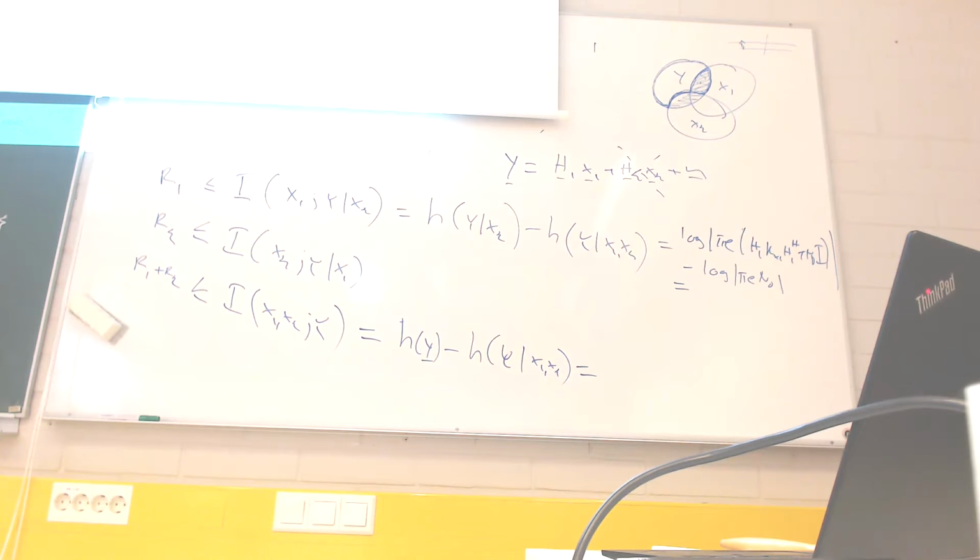You have a pentagon for this pair of transmit covariance matrices, but a different pentagon for a different pair. To come up with the rate region, you have to take a union of all these feasible pentagons. Feasibility means that for any realization of Kx, the power constraint has to hold, and the powers have to be positive. Kx has to be positive semi-definite.